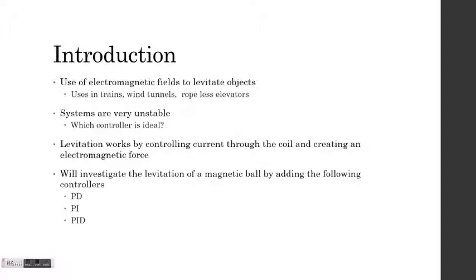This system is very unstable. There are many effects from wind and gravity and the magnet itself. Therefore, for my project, I will be investigating which controller is ideal for a ball elevated by magnets. I will investigate the PD, the PI, and the PID controllers.